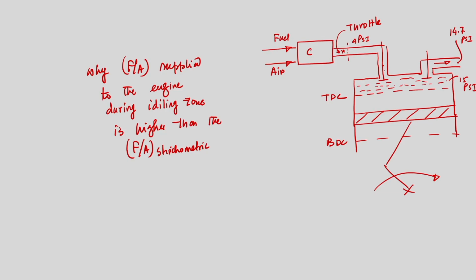Further movement of the piston from TDC towards BDC will then induct that combustion gas along with the fresh charge. Since the combustion product is blocking the path, we won't get the amount we are supposed to get during the movement of the piston from TDC to BDC.